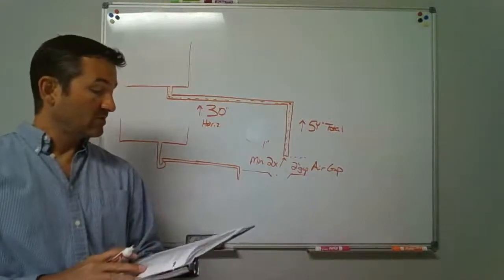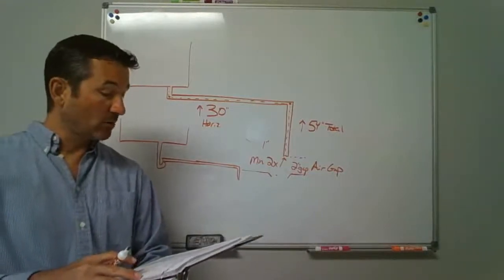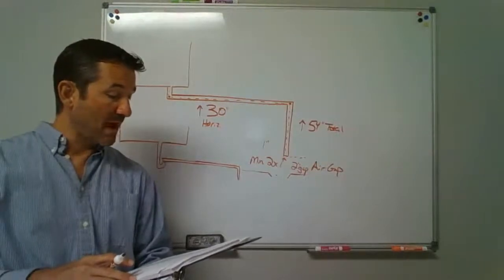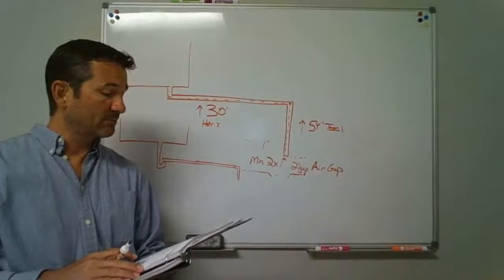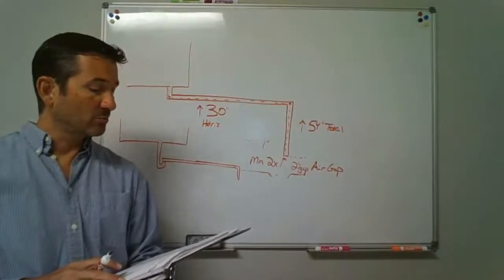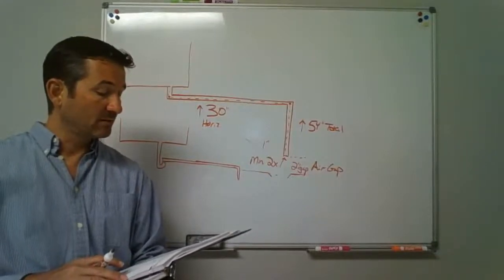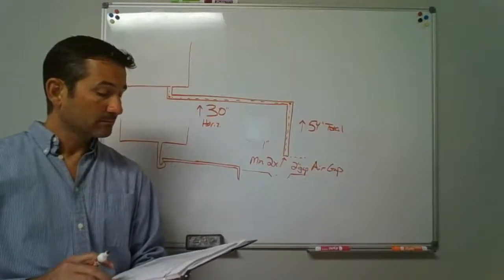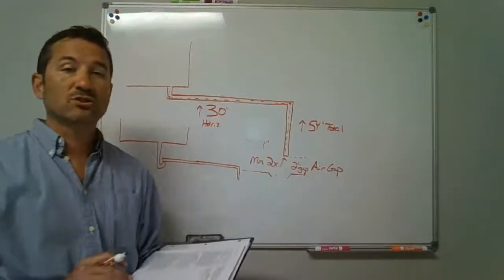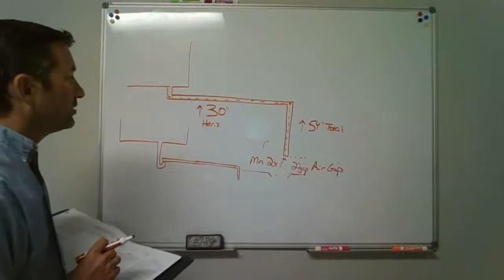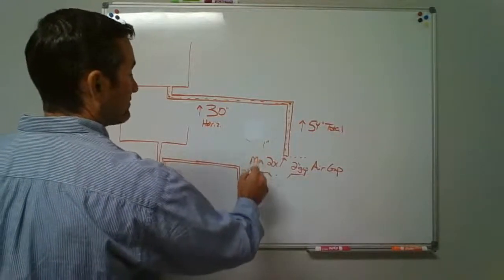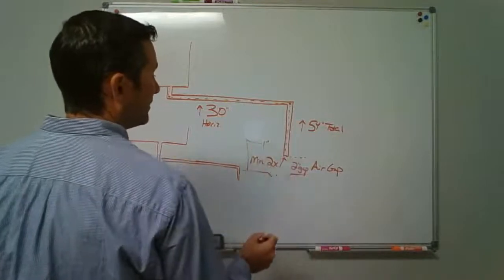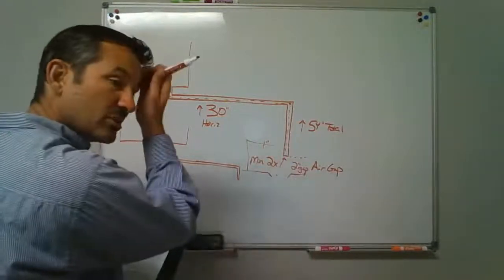Okay. Size of the waste receptors on page 74. Waste receptors should be sized for the maximum discharge of all indirect waste pipes served by the receptor. Receptors should be installed to prevent splashing or flooding. Some means of trying to say, hey, what am I going to do on that thing to keep it from splashing? A lot of times we'll put some type of guard around it or something like that.